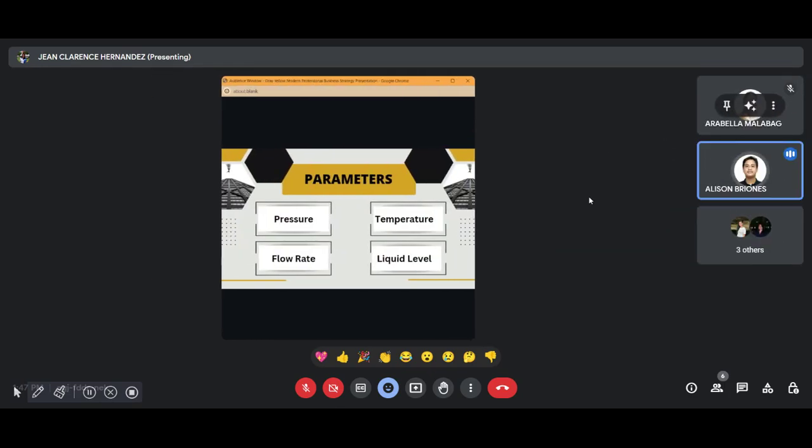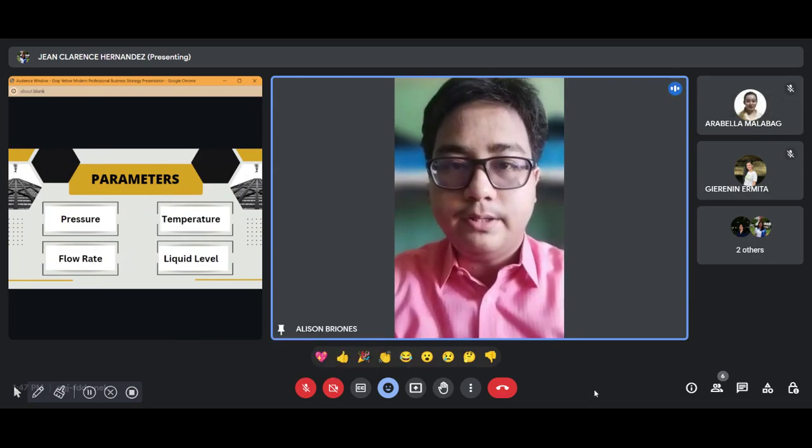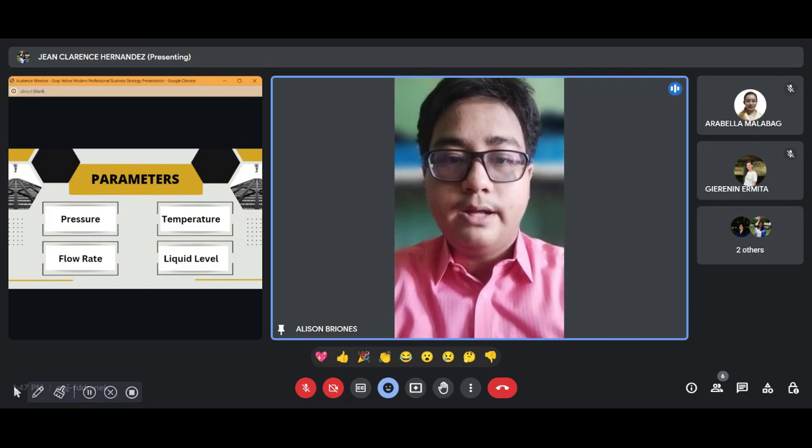Good day. I am Alison Briones, and I will be discussing the parameters as well as introducing the process flow diagram of the glycol dehydration process. The glycol dehydration process relies on four parameters, namely pressure, temperature, flow rate, and liquid level, with each playing a crucial role in maintaining the efficiency and effectiveness of the system. A delicate balance and precise control of each parameter is necessary to achieve said effectiveness, as well as the desired outcome of dehydrated natural gas for processing and transportation.